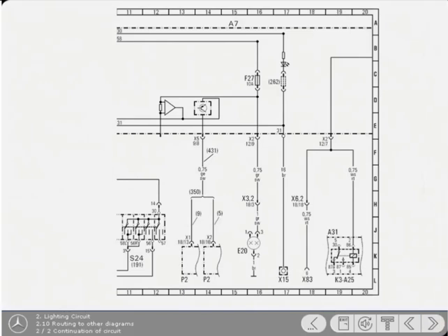Having identified the correct wiring diagram from the search aid, let's explain how this diagram links to that of the instrument cluster. If you remember, the cable you are following was that which connects the bulb monitor control unit with the instrument cluster. To find this cable on the instrument cluster diagram, first note the designation of the component from which the cable is coming.